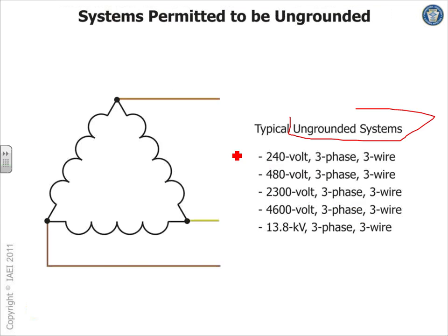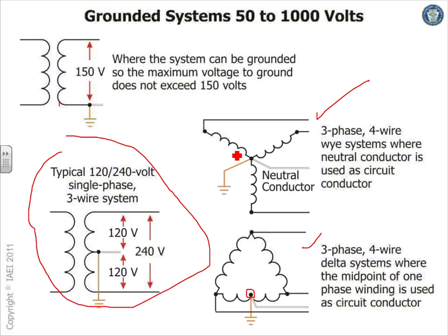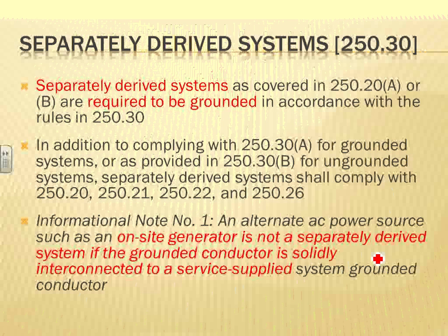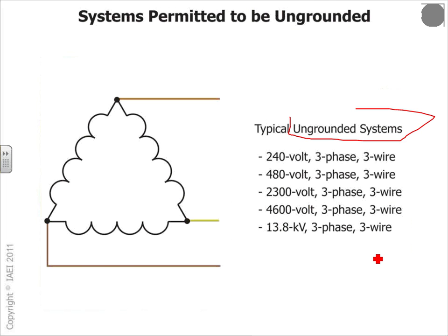And then, so we talked about, guys, the systems that can be grounded and the systems that can't. So imagine going through this one before you even reach the how to ground. This is how to ground. So these are the systems that must be grounded. You can see there are Y or center tap delta or split phase power systems in the second. These are the systems coming in here. These are the systems that can be ungrounded if you want to run an assembly line with them.